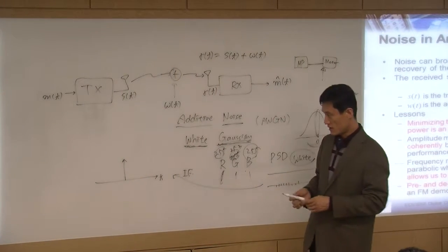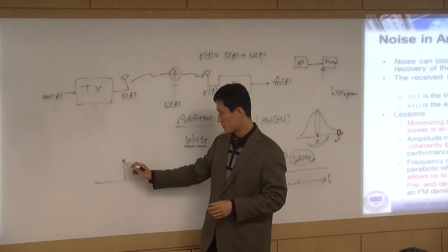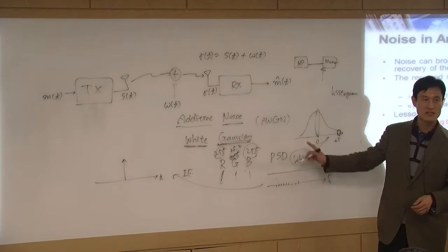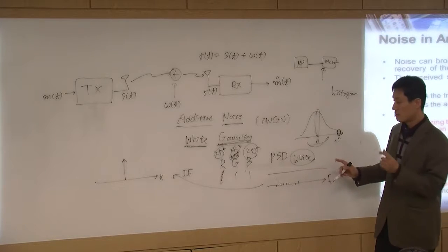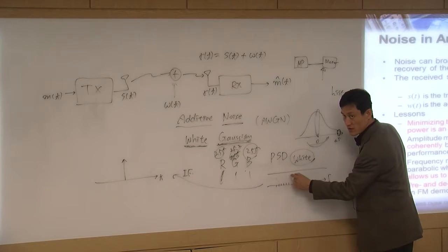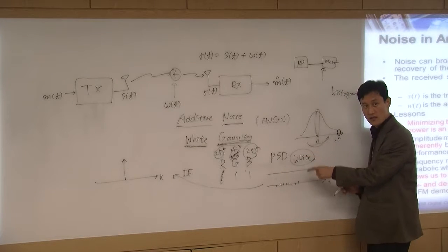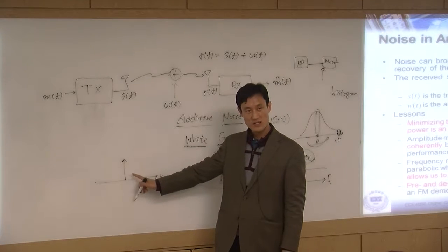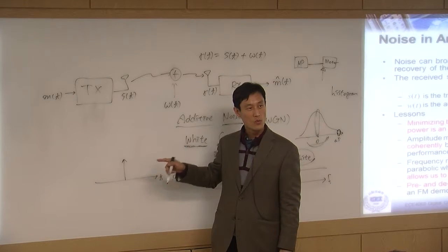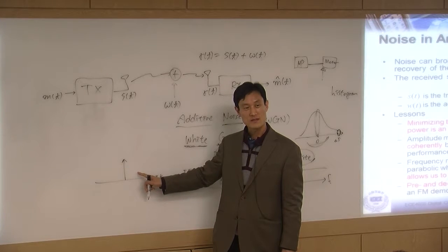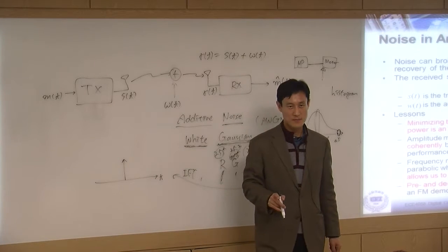We're going to get an impulse. This in the frequency domain we call a power spectral density, meaning how much power is allocated for each frequency. Now let's take an inverse Fourier transform. We get this one in time. What do you call this? What is this in time?